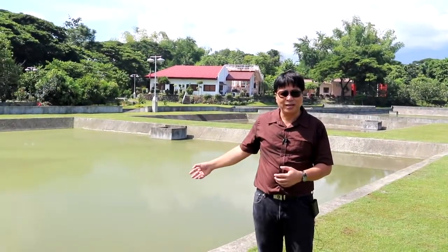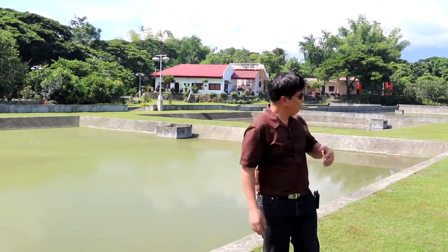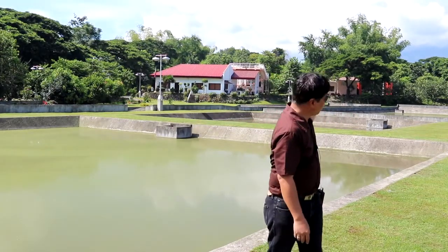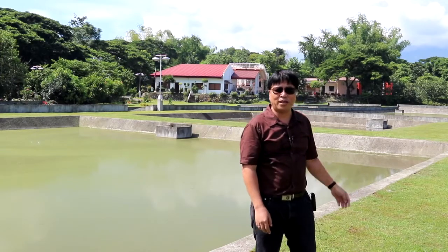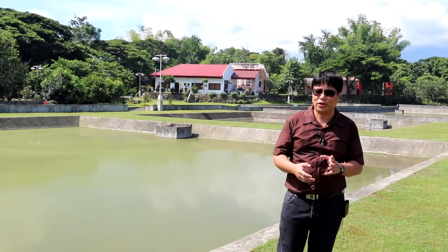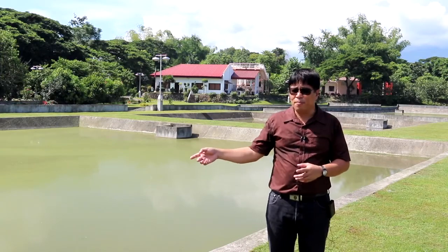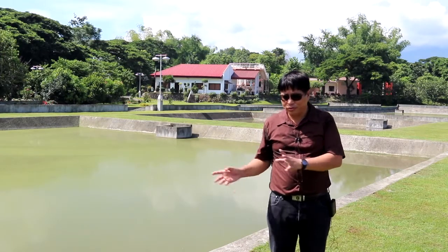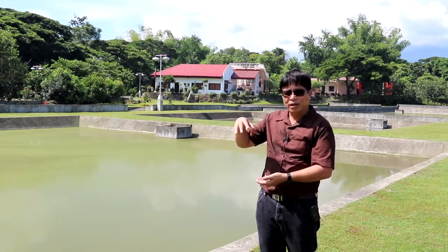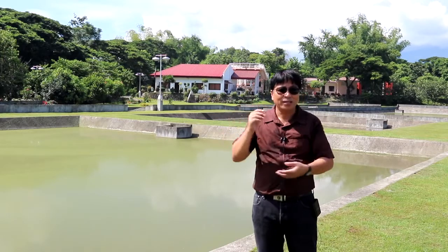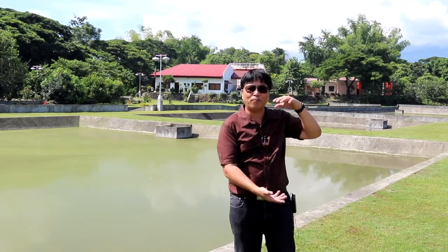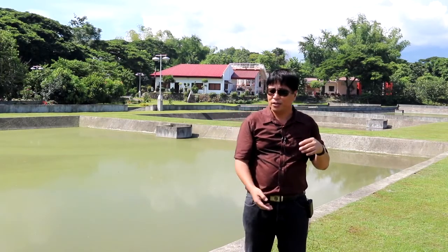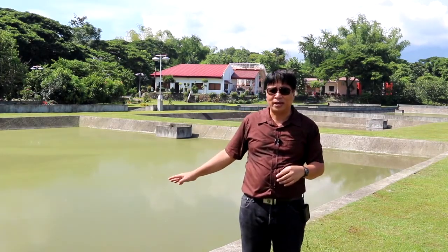Right at my back is the second stage anaerobic pond, but 2 more tanks will be very close to the facultative pond, which I'm going to talk about. The anaerobic ponds, to give a little background, are about 3 meters deep. The facultative pond is around 1.5 to 2 meters. So you can see the difference.